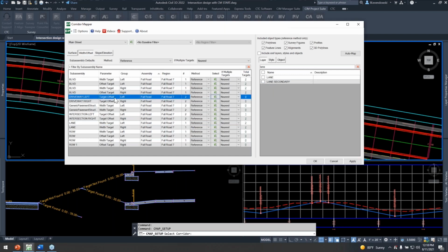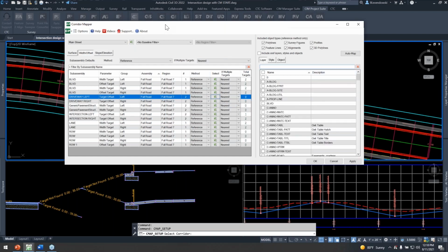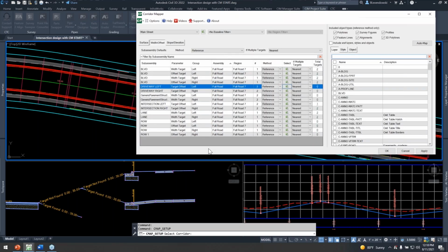We talked about the driveways themselves. I've got simple polylines to be assigned to these conditionals. And again, conditionals, they work great in pairs. Those of you who might be new to conditional subassemblies, always use them in pairs. It gives you a very handy kind of if-else type scenario, whereas if you stack up 3 or more of them at once, you can get duplications in some areas. So I always use them in pairs in this way.